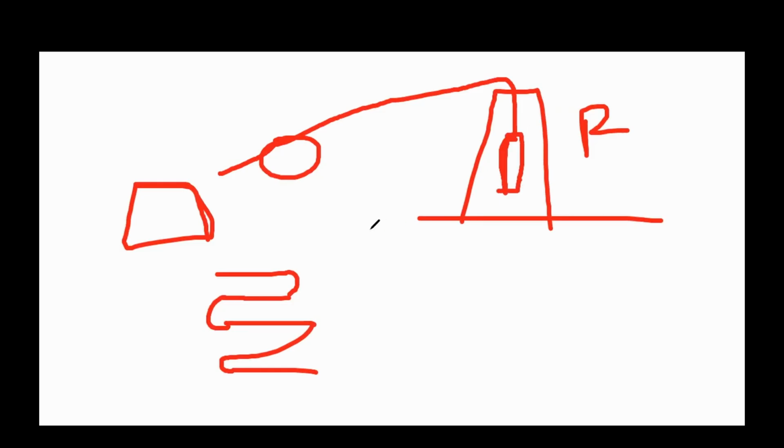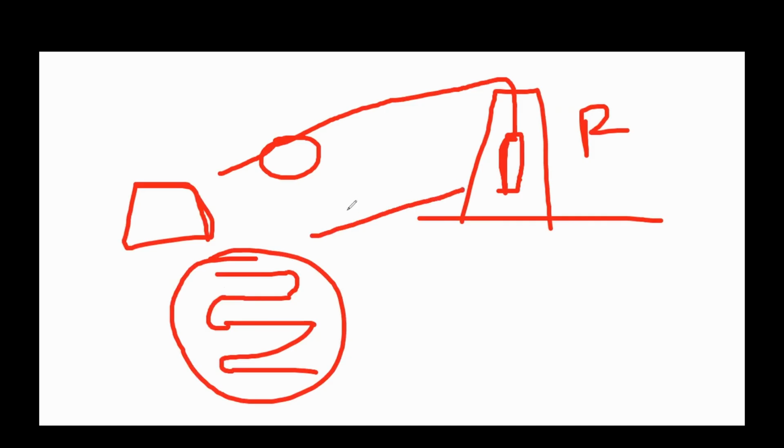Everything, the tools, when they're lowering or keeping them, they'll keep on the ground, and slowly they'll put each one on one sledge type structure that is termed the catwalk. We'll see these terminologies in drilling. On the catwalk they'll lower and rig up. It is termed as R/U, rig up of logging, and this logging tool will slowly run into your wellbore.